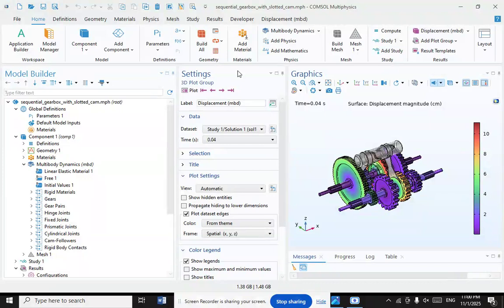Therefore, to speed up or slow down the input shaft as required, cone-shaped brass synchronizer rings are attached to each gear. When the driver moves the gearshift lever towards the next gear, these synchronizer rings press on the cone-shaped sleeve on the dog collar so that the friction forces can reduce the difference in rotational speeds.